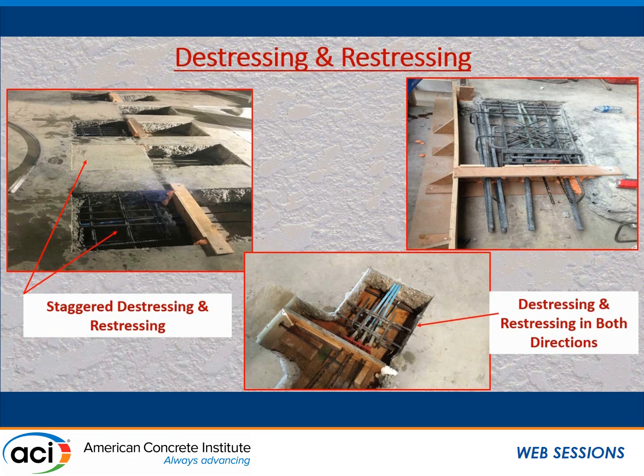In the one in the upper left, because when you're de-stressing a number of cables, then you've got a bunch of shoring. And sometimes the shoring, depending on the footprint of the building and what elevation you're at, can be a bigger number than the cost of de-stressing. And so at times this is what we will try to engineer in, as we stagger the repairs. So you go to a group, you skip a group, you go to a group, you skip a group, so that you can get in there and not have all this forest of shores and do your stressing.